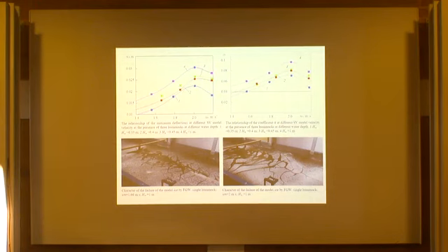The most intensive ice failure and ice piece pushing occurred at near critical velocity. The ice cover completely lost its carrying capacity at the model's critical velocity, and the area of the fracture was reduced significantly. The intensity of destruction at low velocity was higher than at a velocity near the critical value, which is saturated with the crest of flexural gravity waves.